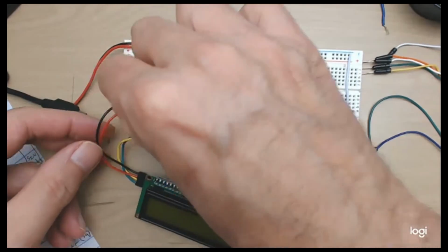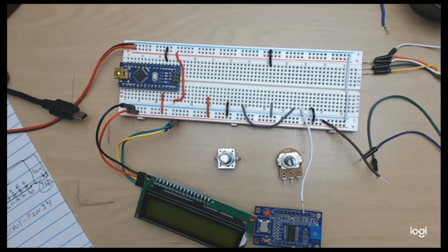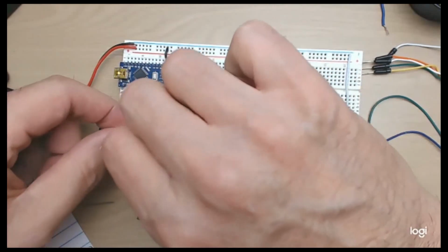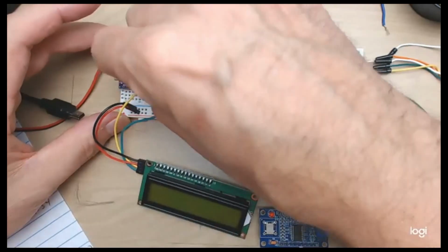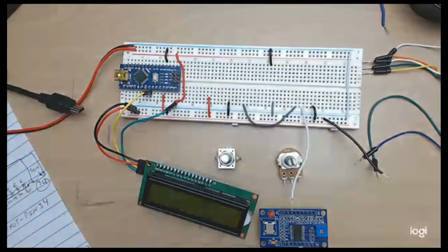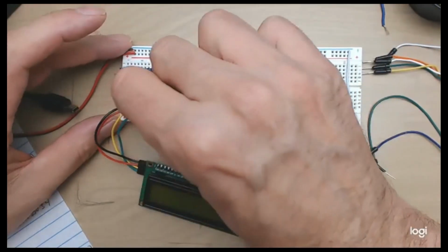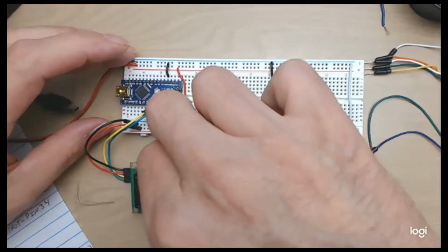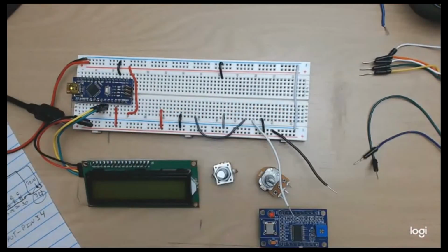negative and the +5. So that's just one into each rail. And then the yellow wire, which is the data wire, goes into the analog number 4 pin. And it's actually printed right there on the pin itself. It says A4. And if I get it plugged in right, that's A4. And then the green wire, which is the clock, that's going to go into pin 5. All right. So, fine business. Now I have hooked up my LCD.